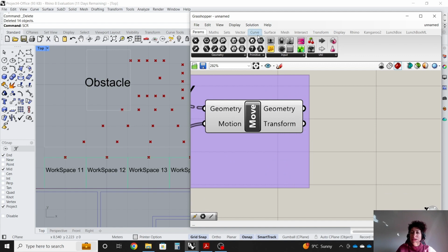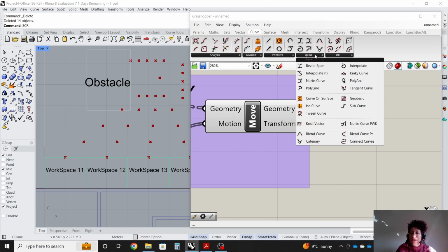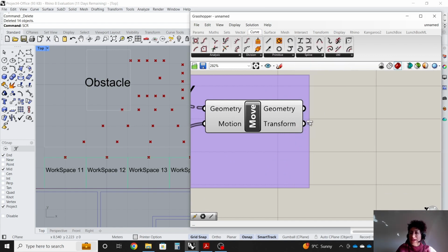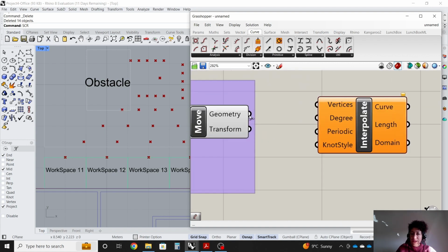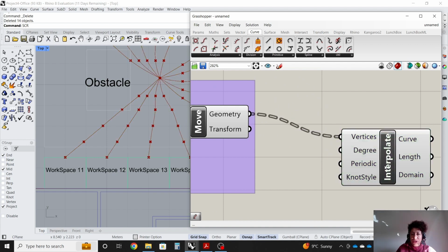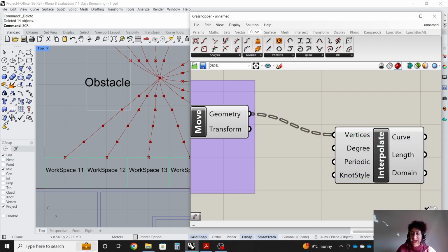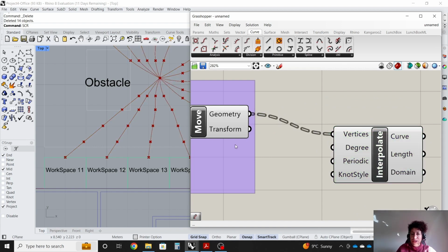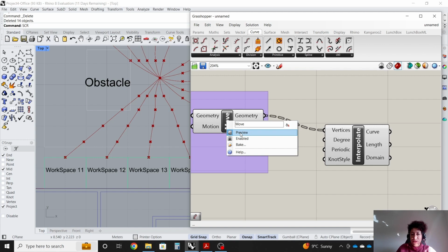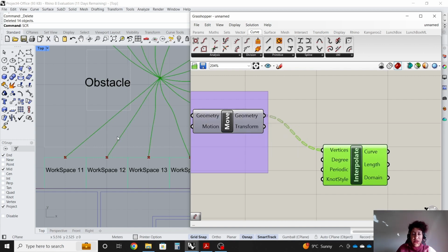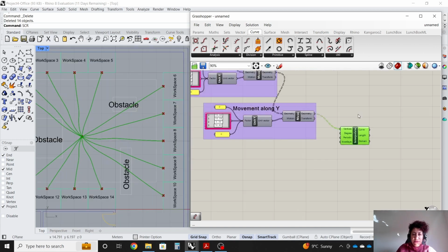So how? I want to go with curve. I think under spline, interpolate type of a line is going to be okay. So I want to assign the points to the vertices, and it's going to draw kind of a path to connect the points. Feel free to hide the previous node so we just see the lines. So this is now the pathways.